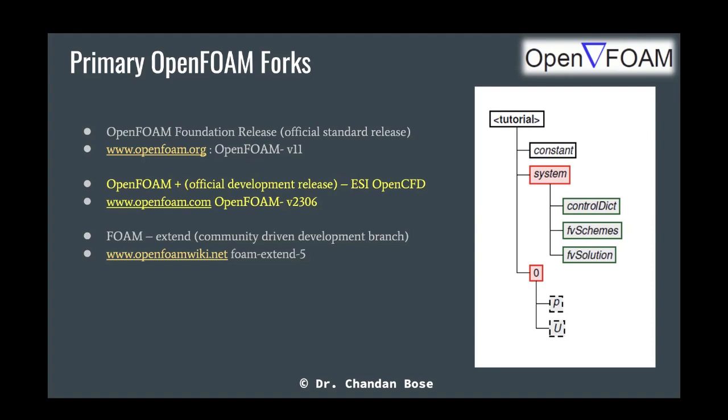Yes, as I told, there will be multiple different files as and when you add more utilities or more complexity. So the one you mentioned, there can be many others, but I told the basic ones which are required to solve an incompressible Navier-Stokes system. The mapFieldsDict, what it does is, if you want to run, for example, an LES simulation, right? For LES or DES simulations, for turbulence simulation, we often want to initiate the solution from a RANS solution of the same problem.